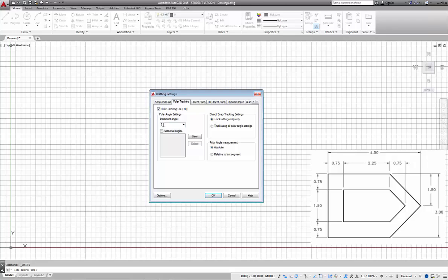If you want to test it, go ahead and type 1 degree and try to create a drawing with a 1 degree polar angle increment setting. It's much trickier to accomplish that task. We're going to leave it as tracking orthogonally, and it's going to be 0 based, or horizontal 0 based, like from mathematics, the angle direction from mathematics, so we're going to use absolute.